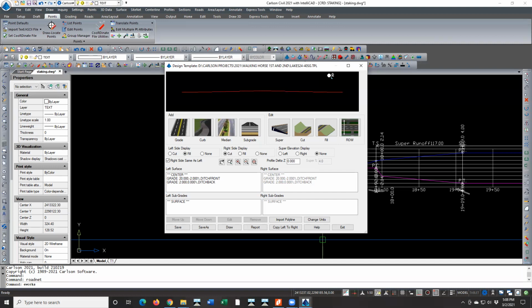I know how far out when I come up a foot at 4 to 1, I'm coming in. I basically run it all in the data collector. So when I go through a super, then I have to change my crossloads every single station till I get to a full super.